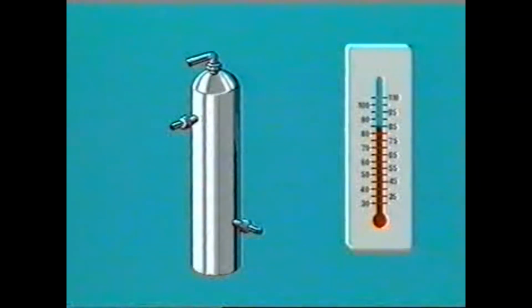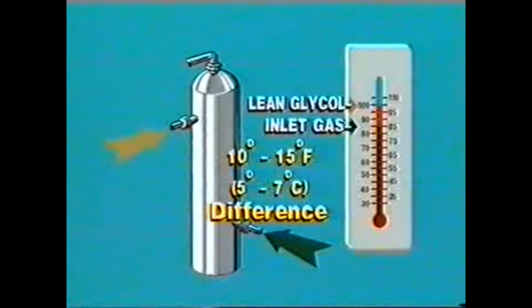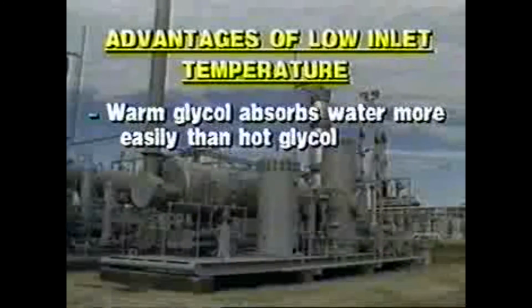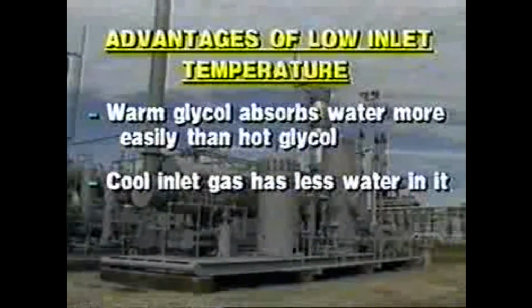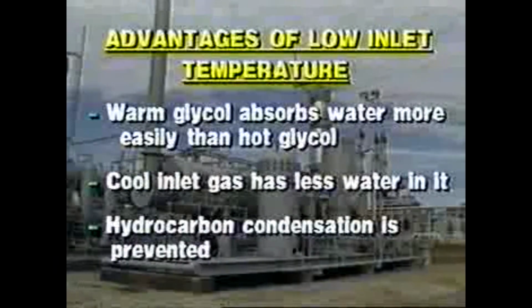Well, it means if we keep the inlet gas temperature low, the unit will have less water to remove from the gas. Now, you also want to keep that lean glycol temperature down to a minimum when entering the contactor, but still 10 to 15 degrees Fahrenheit higher than the inlet gas. Why? Well, for several reasons. 1. Warm glycol absorbs water more easily than hot glycol. Secondly, we're trying to keep the temperature of the gas cool, so the incoming gas has less water in it. And thirdly, this helps to prevent hydrocarbon condensation.